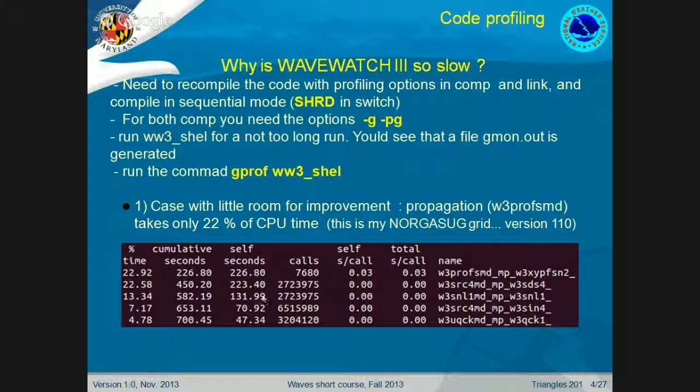It's only 4%. And so based on this table, you can say, okay, well, if really this advection scheme is taking a lot of the cost, then it's worth trying to reduce this. If it's down to 20, 30%, then maybe it's not a big deal to make some effort, and maybe your grid is good enough.